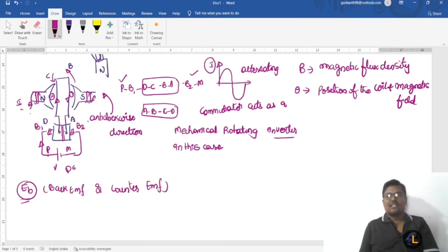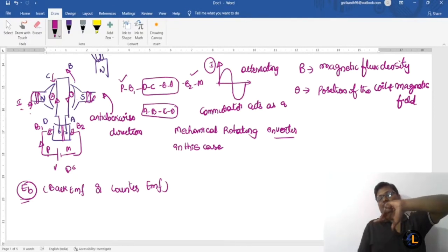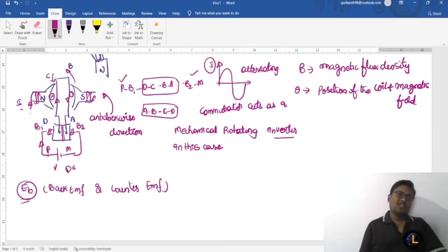See, the rotation of the conductors will be in the downward direction. The magnetic field is from north pole to south pole. You can observe that the middle finger represents the direction of the induced EMF, but here you are not using the left hand rule. You can use the right hand rule for the direction of induced EMF.